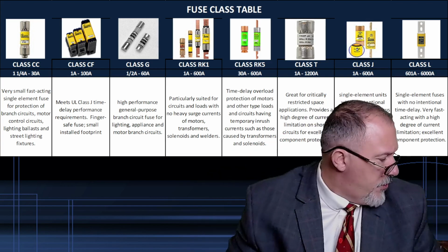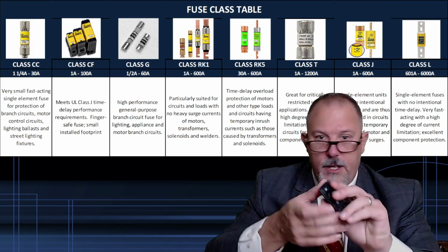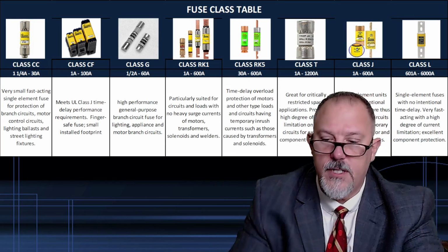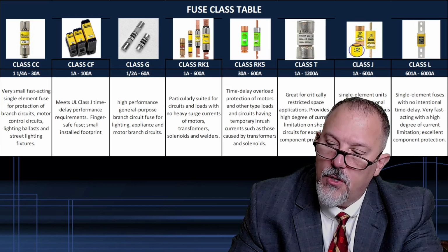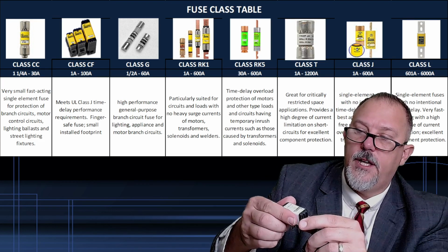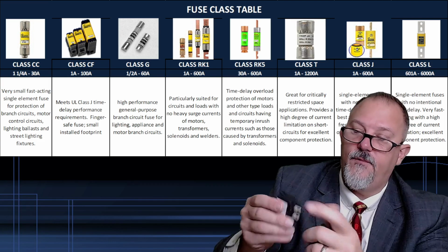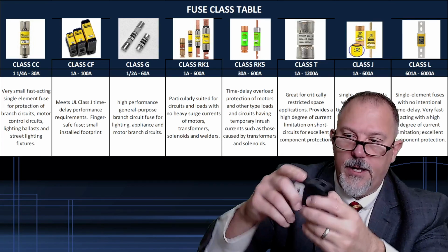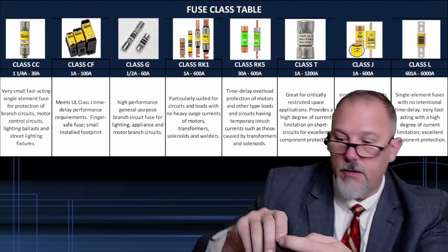The cube fuse has its own holder, right? So here is a holder for a cube fuse. Here is a cube fuse. So this is a 60 amp cube fuse holder, and I'm going to see what this fuse rating is here. This is a 30 amp fuse, and it fits in a 60 amp holder. So this holder, although it's rated for 60 amps, it can hold fuses smaller than that.